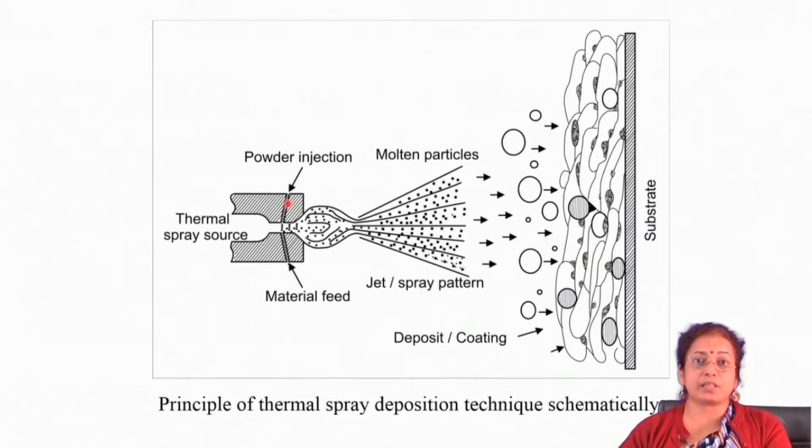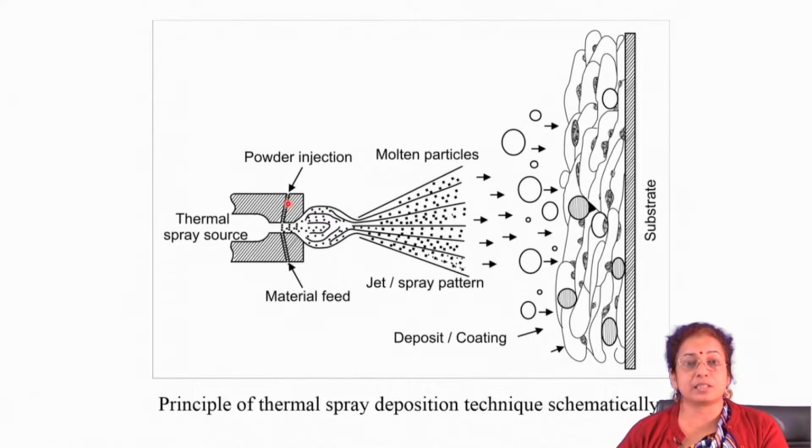Certainly, nano size does not mean that the powder particle size is nano dimension; it is the grain size or crystallite size that is nano in dimension. So, the grain size or crystallite size may be nano sized or micro sized, but the actual particle size should be in the level of 45 to 60 micron and should be flowable.